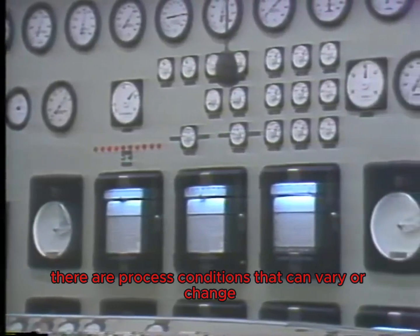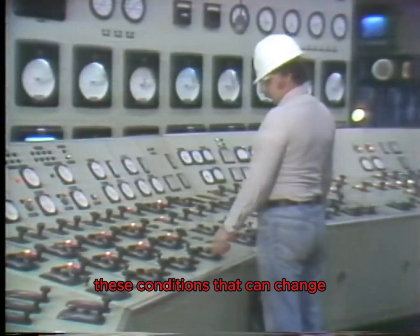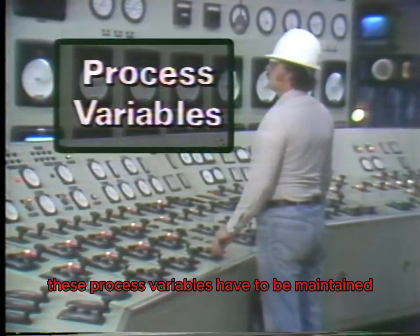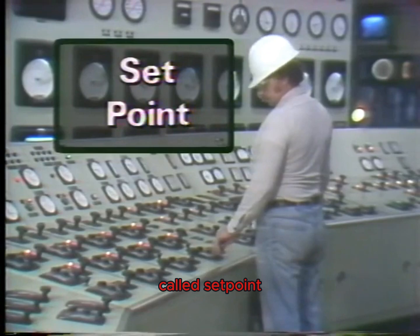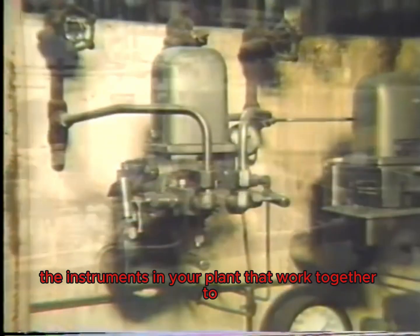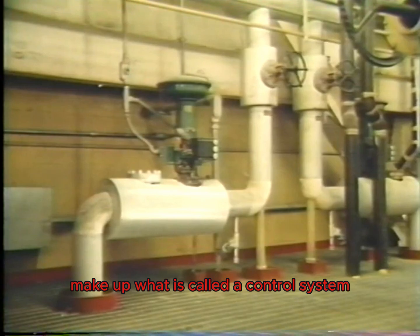In your plant, there are process conditions that can vary or change, such as temperature, pressure, flow, and level. These conditions that can change are called process variables. Frequently, these process variables have to be maintained at or near a desired value, called set point. The instruments in your plant that work together to automatically maintain a process variable at or near set point make up what is called a control system.